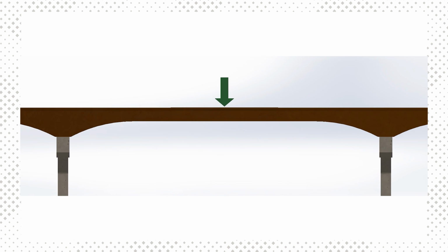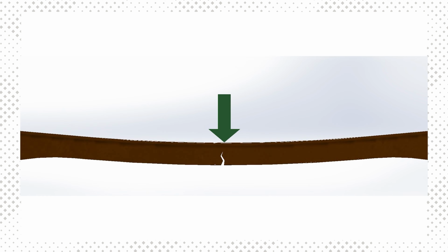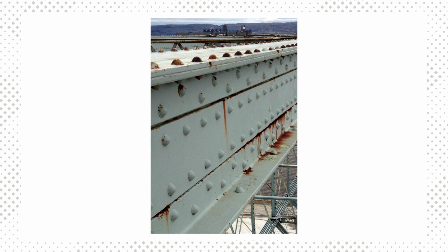System redundancy can be achieved by continuous beams over interior supports or other three-dimensional force transfer mechanisms, such as cross frames. System redundancy must have adequate capacity to carry loads in a damaged state. Internal redundancy exists in bolted or riveted, built-up members. If a crack propagated through the middle plate of this member, there is a high probability it wouldn't propagate into the other elements. The angles and top plate could still carry substantial force.